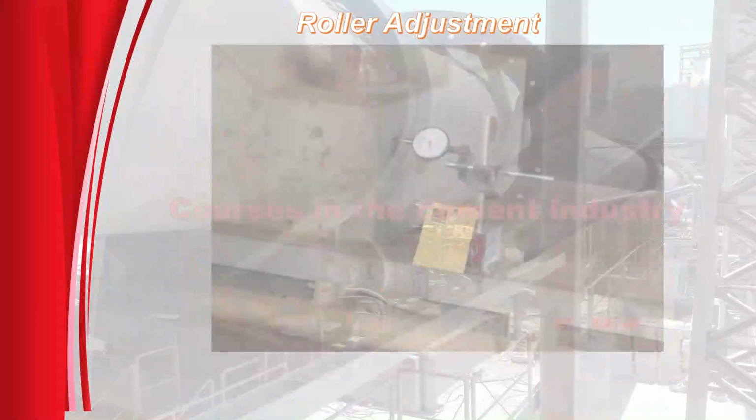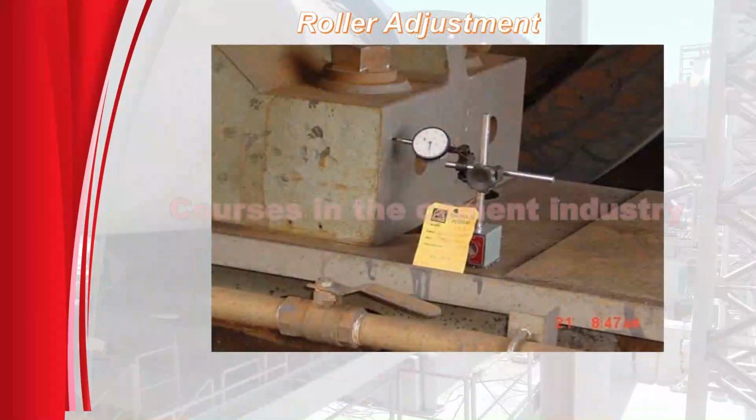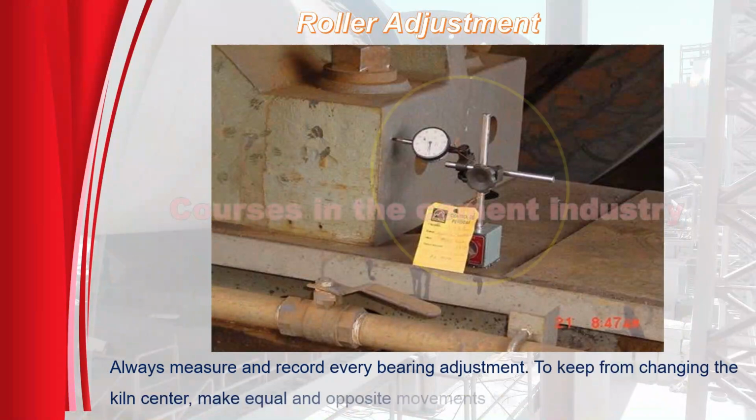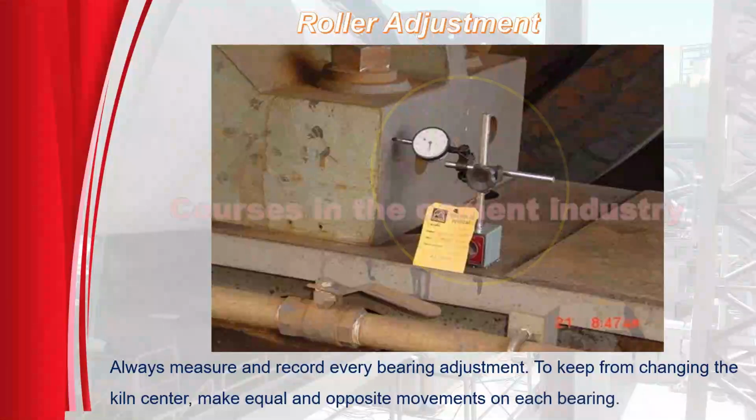In this step, as shown in this figure, always measure and record every bearing adjustment. To keep from changing the kiln center, make equal and opposite movements on each bearing.